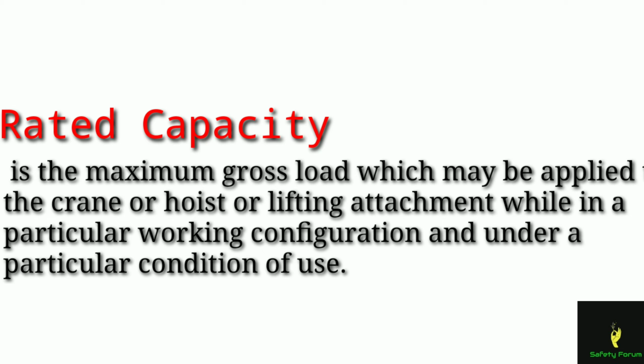So what is rated capacity, which is also known as manufactured rated capacity, MRC? It is the maximum gross load, friends. It is not the net load, it is the gross load which may be applied to the crane or hoist or any lifting attachment while in a particular working configuration and under a particular condition of use.